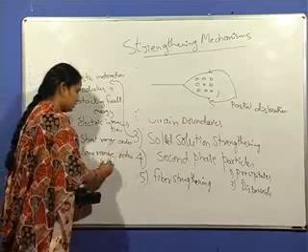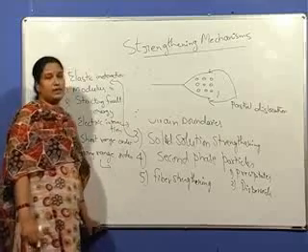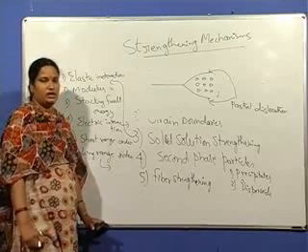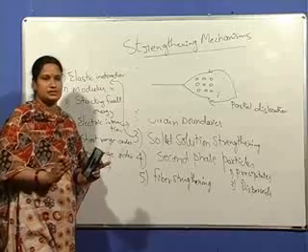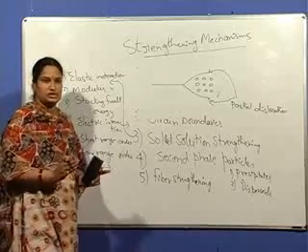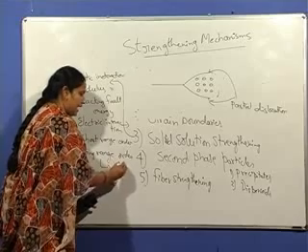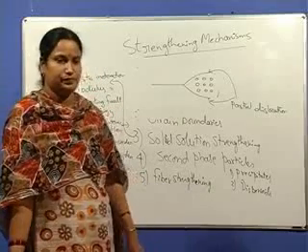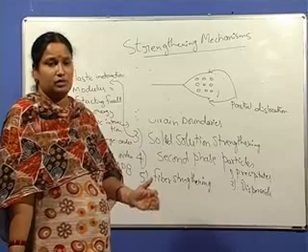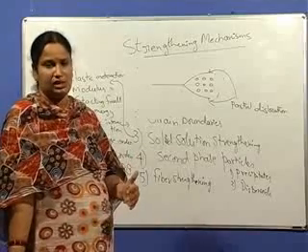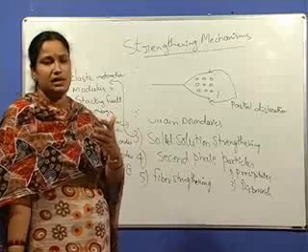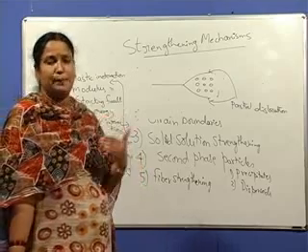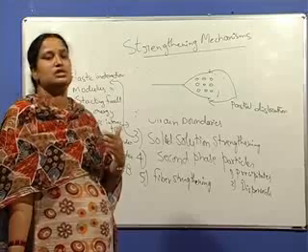And short range order is mainly seen in some types of alloys. Example, superalloys, nickel based alloys, where the formation of ordered regions creates anti-phase boundaries. APB stands for anti-phase boundaries. They are also associated with some energy. So for a dislocation to pass through this requires more energy, and moreover ordering increases with increase in temperature. Thereby for the dislocations to bypass these obstacles or to move through this is very, very difficult.